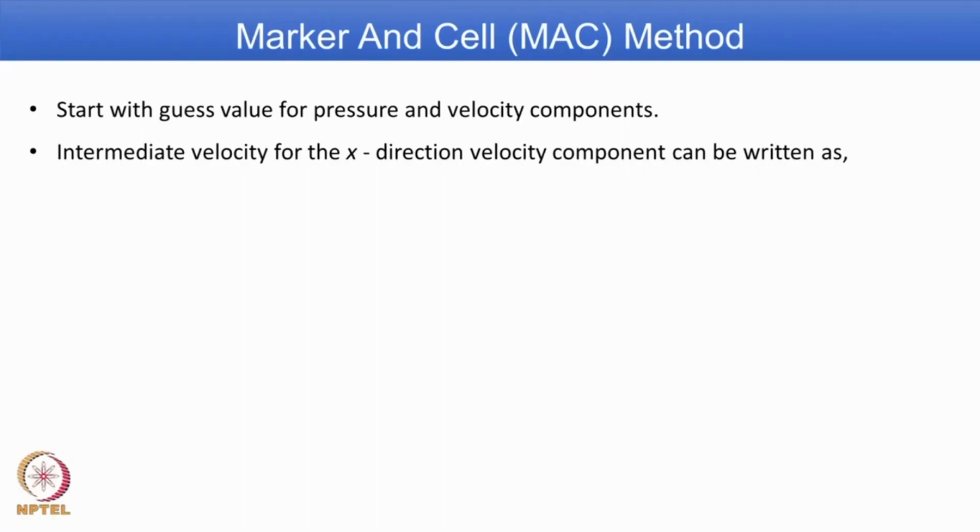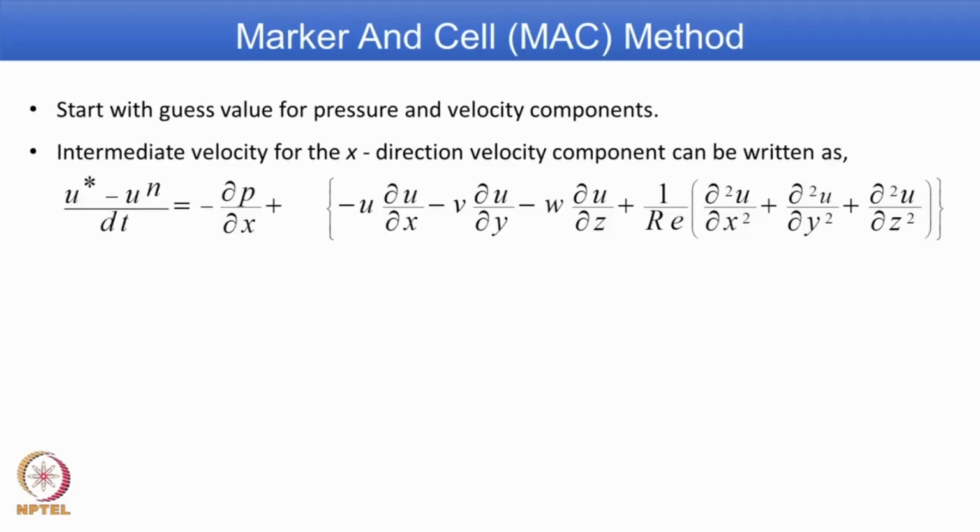We will now explain the procedure for u momentum equation. The procedure is same for v as well as w momentum equation. Between time level 0 or between one iteration to the next iteration, the velocity is intermediate velocity. Once you know the procedure for discretization, then you write down final discretized Navier-Stokes equation. In this case, we mentioned we will take x momentum equation, and that is what is shown here. So, the time derivative term is retained on the left side, all other terms are brought to the right side, which means all the terms are supposed to be known on the right side.